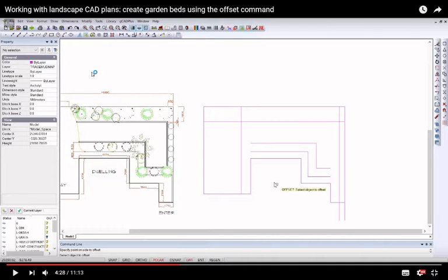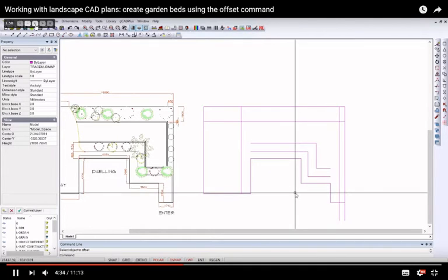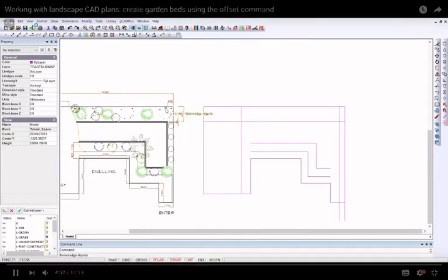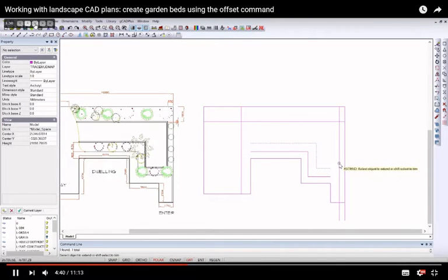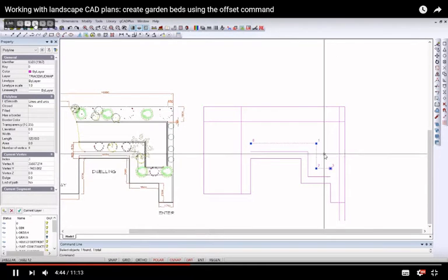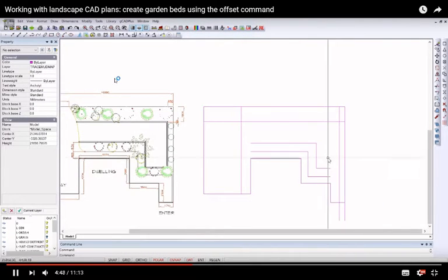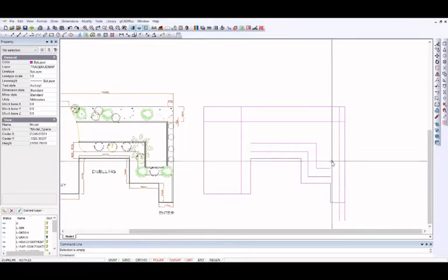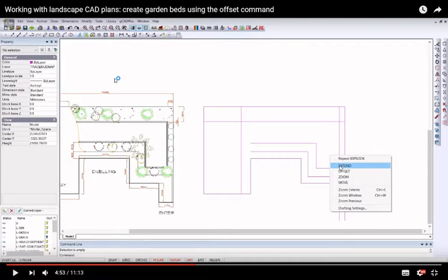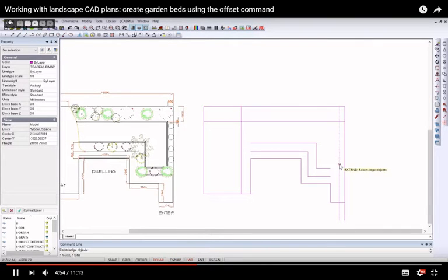Now above 40% faster, have a listen. And we'll exit from there. It's probably time to clean up 50%. So we'll modify and extend this line here through to that boundary, and that doesn't work because we have a polyline, so we need to break it up, explode it, so now we have a single line here, and we have a boundary that we can. And that's 60%. It's still quite usable. Extend to, so we pick it, and now we can extend that line. 70%.